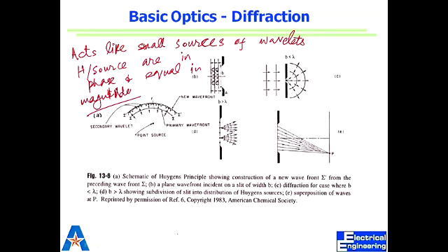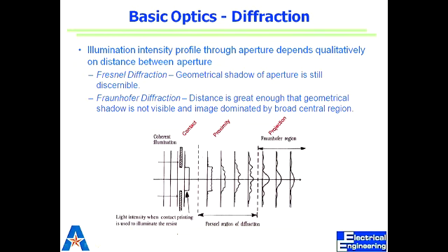How do they come into play with what we are doing? We are making many slits in our masks, right? These are all small transparent openings, and light goes through. The discussion of how small a feature we can make with respect to the wavelength will come later. But before that, we now have these many sources of light, of wavelengths, which will interfere with each other. What we get on the surface will have this kind of shape, and as we move the mask away from the wafer, these interferences become large in wavelength.